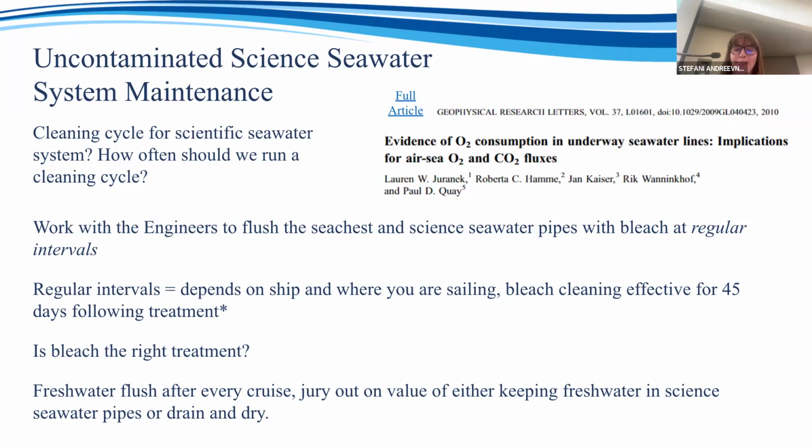It is possible to get it set to not pulsate. I don't know if you can make it super quiet. Those valves seem to click no matter what, but it is definitely possible to get it to run pretty well. I don't know how long they'll last before they, I think, heat check valves at times. But there is hope for them. And I think if you are able to plumb the system so you can run them at an optimal speed, they're supposed to be low pulsation at that optimal speed.